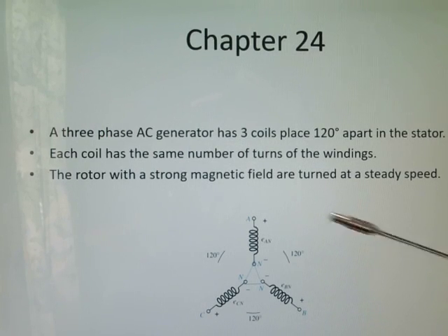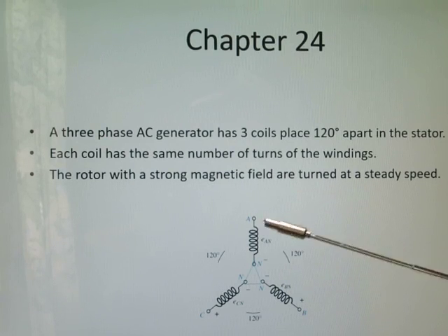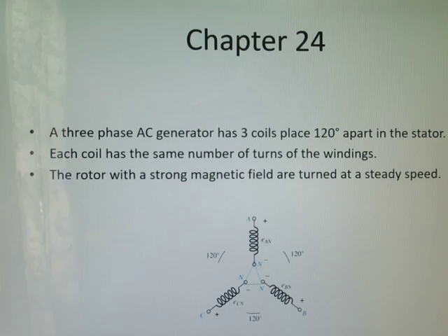Now the rotor, which isn't shown in this drawing, moves past each of the three coils to develop the sinusoidal voltage. Each coil is identical and they're spaced 120 degrees apart. For the 60 Hertz system that we use in the US, the rotor in a 60 Hertz generator covers the full 360 degree rotation in 16.67 milliseconds, which is 1/60 of a second.